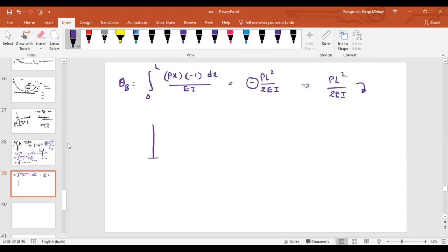Now, in the same way, there is a deflection. Sorry, again, the same problem I am talking about. P, the length is L. What if I ask you to find the deflection at x equal to L by 2, L by 2 from the fixed support? Let us say A, B, C. Can you quickly apply and tell me what is the horizontal deflection at point C? PL cube by 24 EI, sir. Capital M won't change, right? Only the change will occur in small m, isn't it?